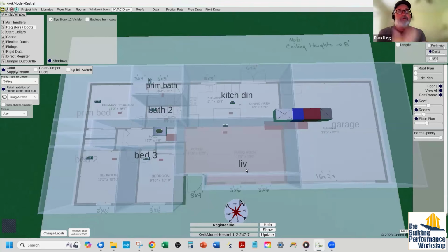So you found your fan table for your 2-ton fan coil unit, and it says it'll put out 800 CFM at 0.4 inches of static pressure. That's the only numbers you need to know: 800 CFM at 0.4 inches of static pressure, as far as Manual S goes. Okay.